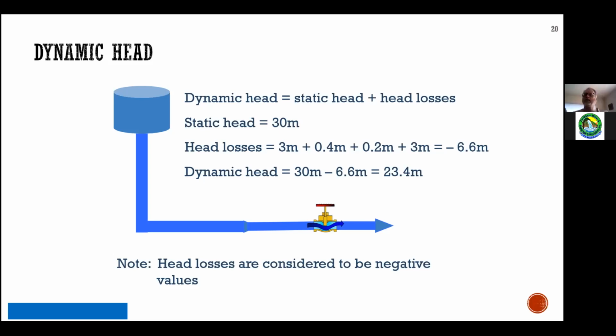So we minimize head loss by either straightening out the pipe, increasing the size of the pipe, or making sure our valves are open. Some of that is done at the design stage by the engineer. They design a 200 millimeter pipe for the system as opposed to a 150, based on expected demand and flows, etc. But as operators, making sure that we don't leave valves closed is critical, because one valve by itself, well, could be a problem.